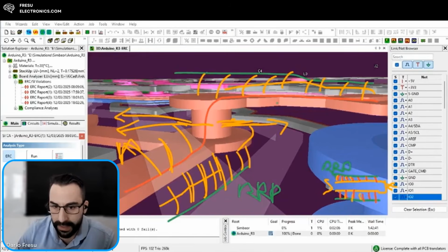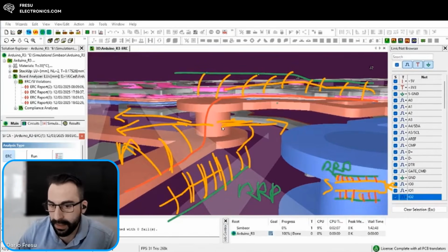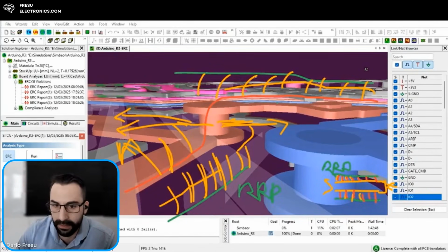So if I have any other copper or metal structures in here, they're going to couple to that. So if I have a signal, like in this case in here, you see there is this other via, then the fields most likely are going to be established so that I have the reference. But then this point in here still needs to close the current loop. So where is this current loop established? It's hard to say, but most likely it is not a current loop that I want to have in there.